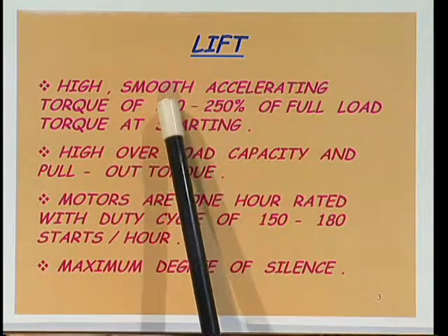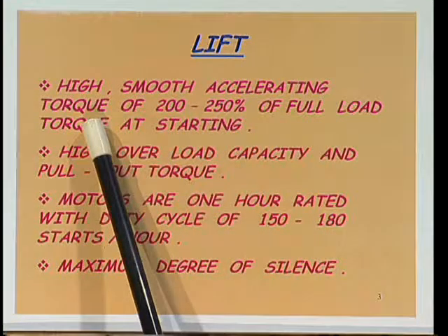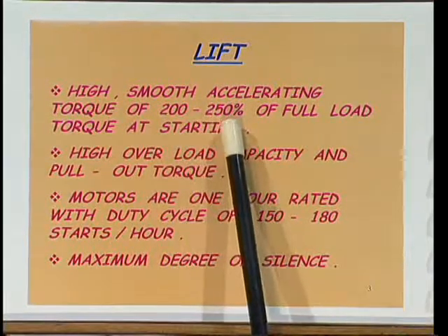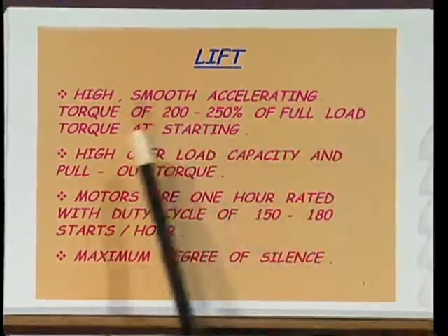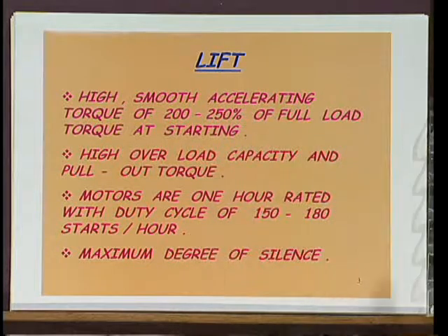Normally for the lift, the motor used will have very high accelerating torque: high, smooth accelerating torque of 200 to 250% of full load torque at starting. The torque exerted will be very high and smooth.